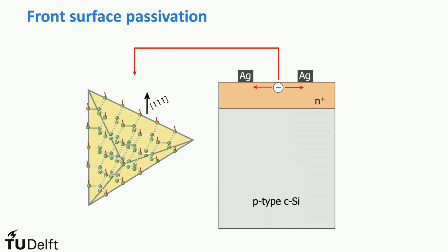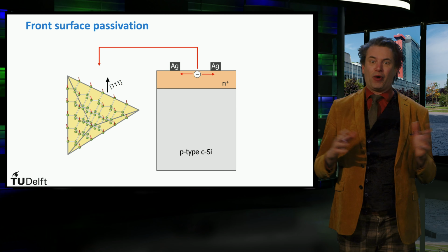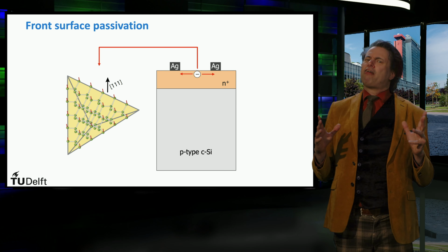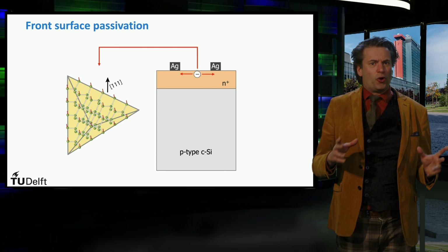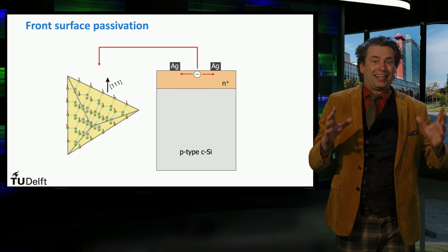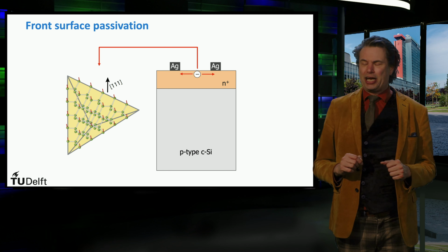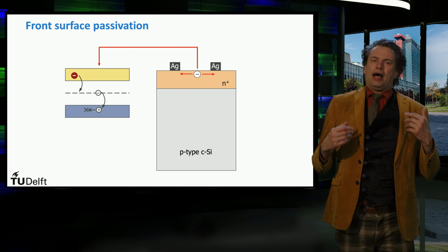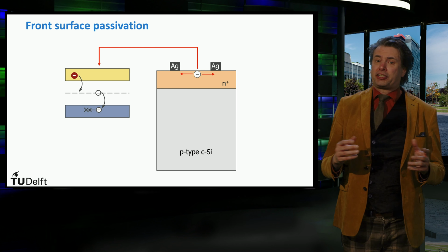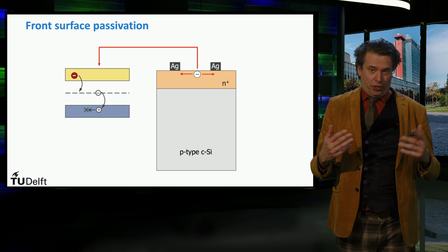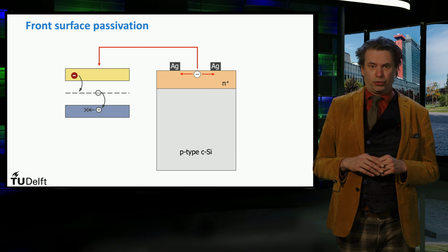First, the bare crystalline silicon surface contains many defects. The surface silicon atoms have some valence electrons which cannot make a molecular orbital with the absent neighboring atoms, here indicated with the red lines. These valence orbitals containing only one electron at the surface act like defects, also called dangling bonds. At these defects, the charge carriers can recombine through the earlier mentioned Shockley-Read-Hall process.